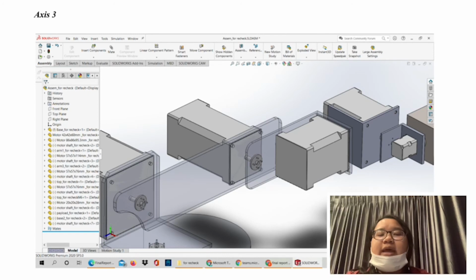For motor 3 in axis 3, it is inappropriate for this design. The motor 3 has 3 Nm. That's enough for the required torque of 2.199 Nm, but has an inappropriate size because it's big. In this case, we can use the timing belt to apply the torque and decrease the size of the motor.